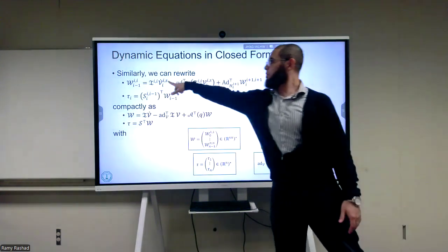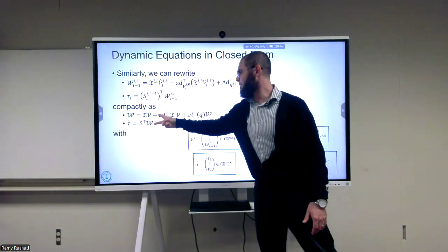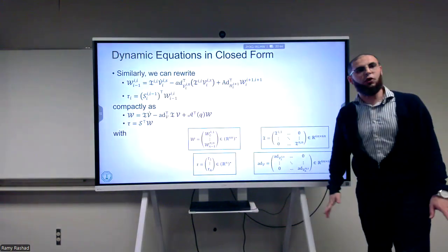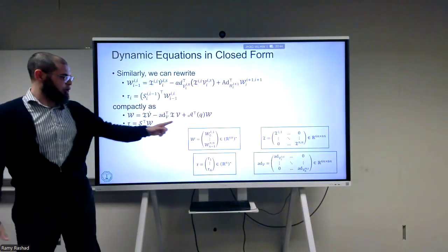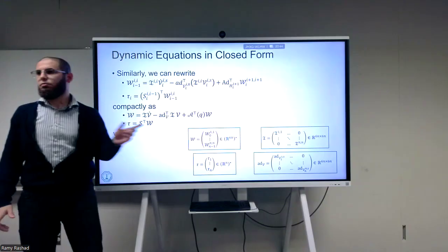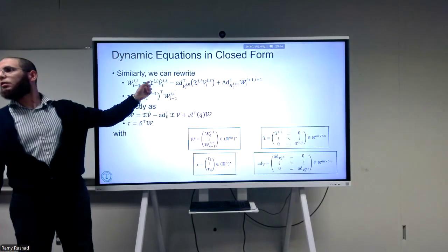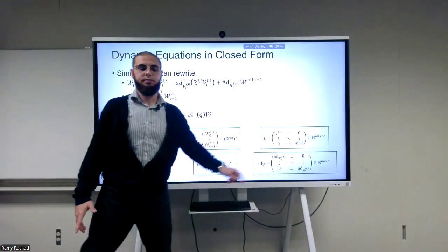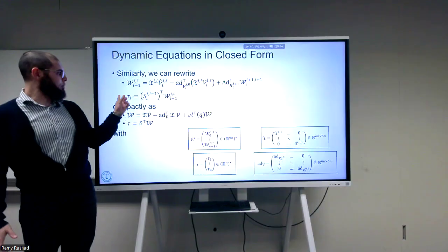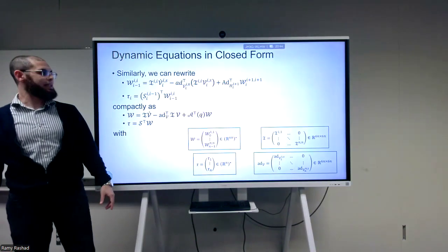For the wrench, for this top equation, and for the twist, I can write them as these two equations by doing the following. All of the wrenches, I can stack them on top of each other. All of the inertias that were here, I put them in a block diagonal matrix of this form. And the tau, all of them, I put in one big stacked vector.